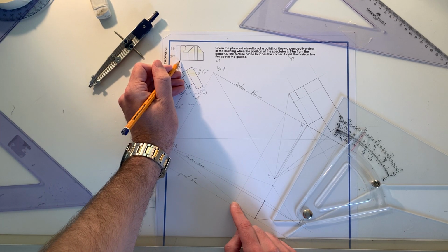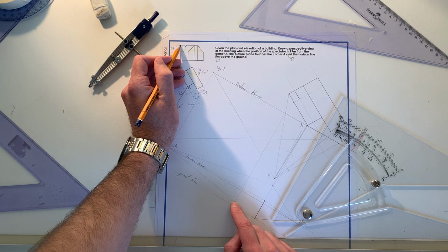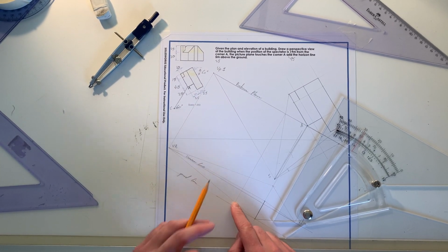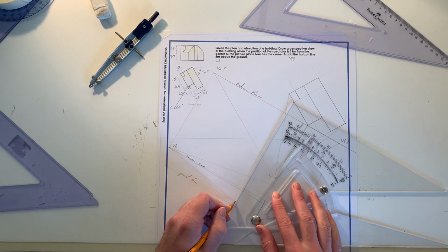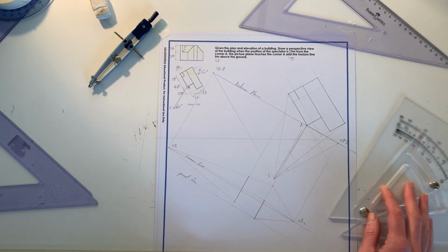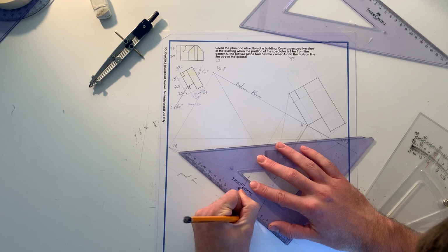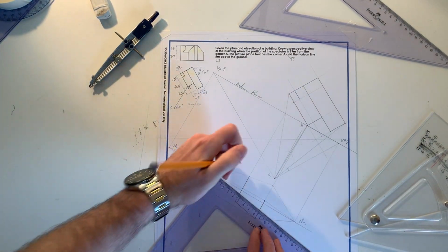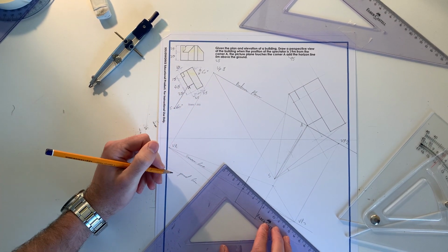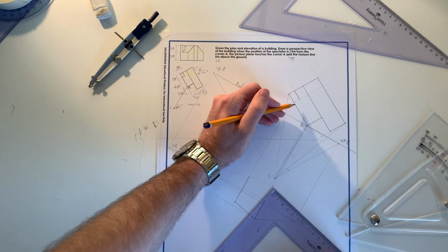Now I also need to locate the top of my chimney here. To locate that, that will actually be along the line represented here, where that's carried back. So if I extend this all the way up to that, that's that line found. This is this line found. I can also join this line back to my, that's fine. I can carry this point there.